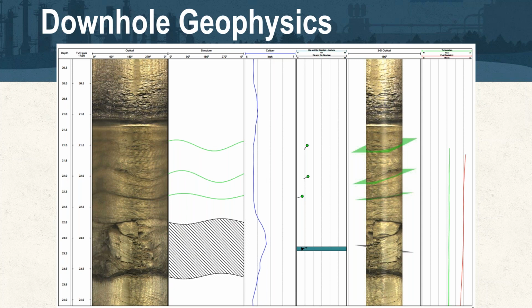There's a number of questions here about the tooling itself. Some of you have asked the biggest differences between ATV and OTV. Briefly, ATV is an ultrasonic acoustic image that's inferred, and the OTV is a physical image. It uses a CCD sensor, just like what's in your DSLR cameras. So that's a true actual photo downhole of the borehole. There's some other questions here about calipers and HPFM. So we'll reach out individually because that's a lot to digest here.